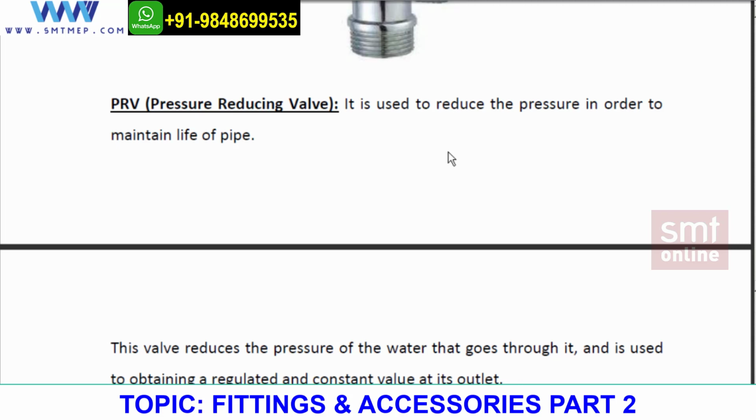Don't you think the water coming from 30 floors of the building, when it reaches the ground floor, crosses 60 or 80 psi? Will it or not? Yes, for sure. It will be almost 300 psi, which is not at all recommended, because as per some table in IPC, we know that there is a standard pressure and GPM which every fixture demands. If I get more than that, the fixture will get damaged.